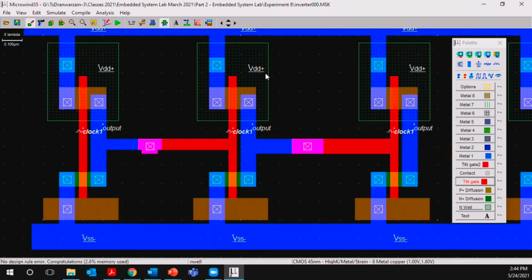Okay, so if you do not put this contact metal and poly, that means you will observe a connection between this metal and this metal, because these are different metals. So you should contact with this via, or metal to contact. If you want to use another metal, you can use metal 1 and metal 2. If you have different metal 1 and metal 2, you should use this contact, meaning that it should be a contact between two different layers.